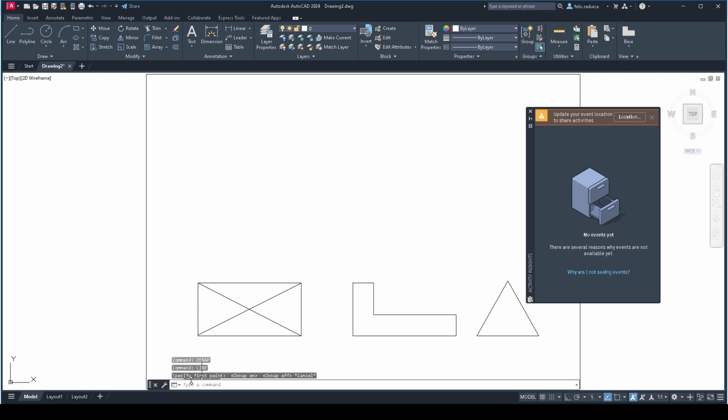Okay, it should say here ortho off. Okay. So to use this more efficiently, I will use a secondary command after I type in the line command. So first I'll type in the line command. And after typing in the line command and disabling the OSNAP, if I want to snap to the middle here, I have to type in MID for middle and enter. And now my cursor is only snapping to the middle.